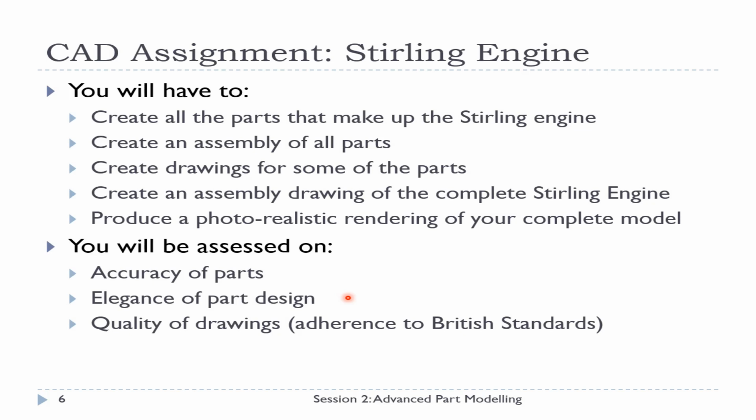So basically how you structured your parts, how you used design intent, how you made your sketches fully defined, or models that can easily be modified if that's required. So you should pay attention to how you modeled your parts. And the most important bit is the quality of your drawings.